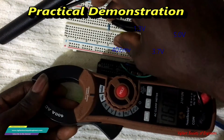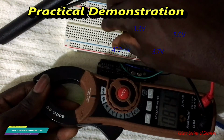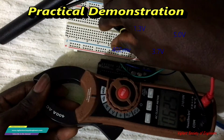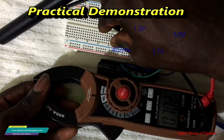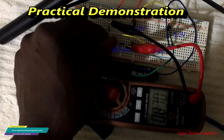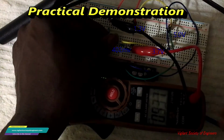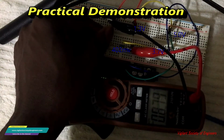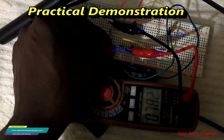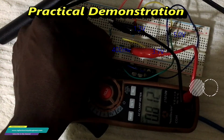So this should have been equivalent to the 1.14 or maybe 1.1. All right, so we're going up, you can see we're climbing to 0.9 roughly. So I'm saying there's a voltage drop or losses within the circuit because we're not 100% in contact within this board, or breadboard, so we incur losses within the circuit. All right, so I'm roughly at 8.40, 8.6 and counting.